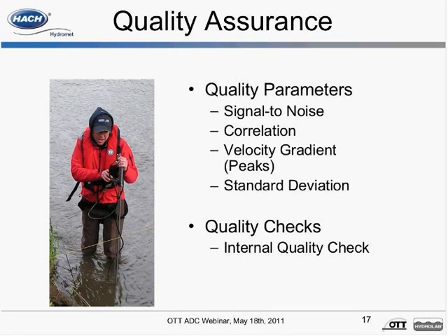If the 50% standard is not met, the measurement is rejected and the user is prompted to repeat the measurement. If the measured values are confirmed, the ADC calculates the mean and standard deviation for the measured velocities in the cells closest to and farthest from the sensor. Based on the result of the calculation, the final velocity is determined and shown in the display.